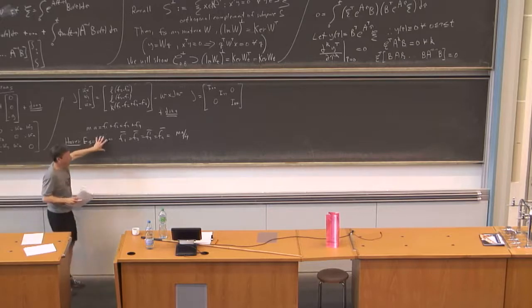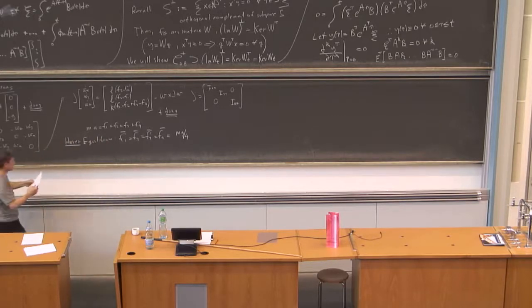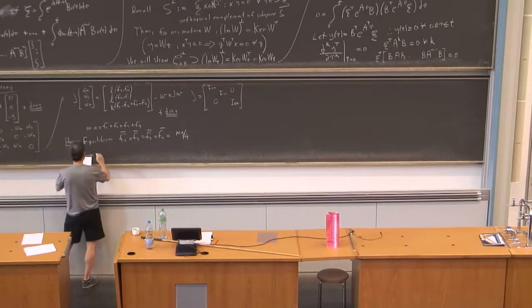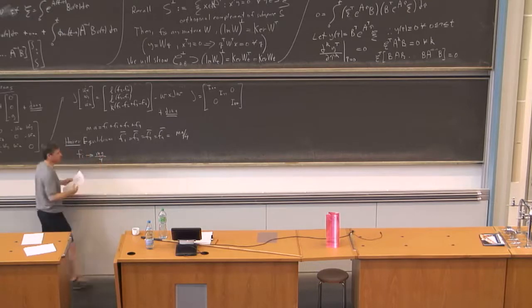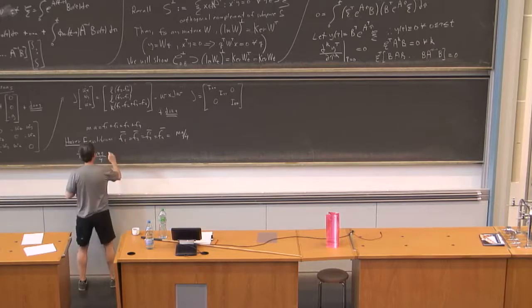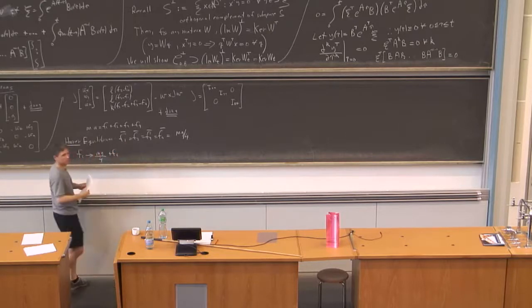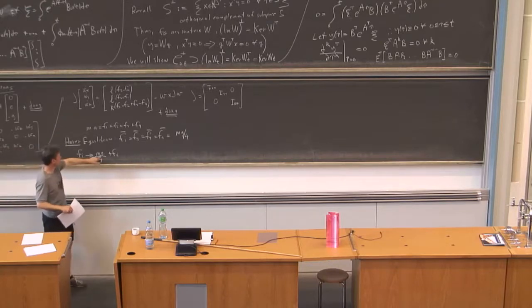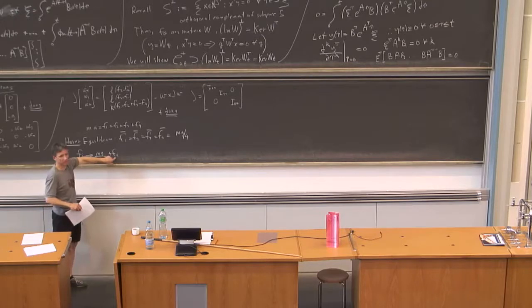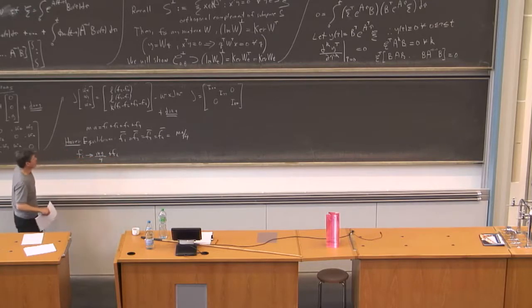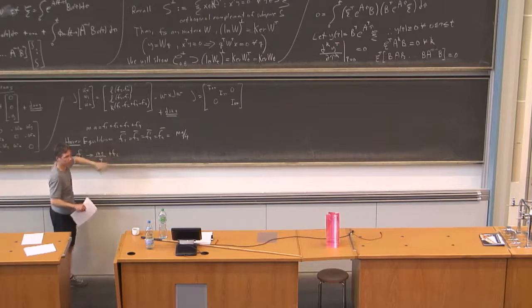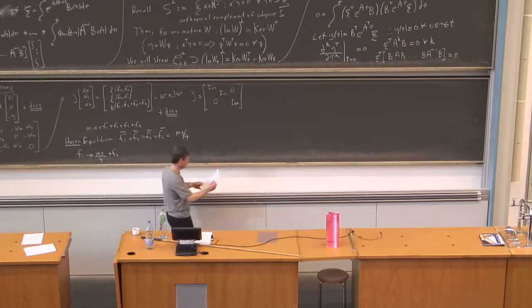So we want to analyze the system about equilibrium. So I'm going to take my Fi, and I'm going to map that to mg over 4, which is nothing but the equilibrium thrust, plus Fi. Instead of defining a new variable, I'm just saying take my Fi's everywhere in here and substitute mg divided by 4 plus Fi. So Fi before was the total force, now it's the perturbation about the equilibrium. That way I don't have to define new variables.